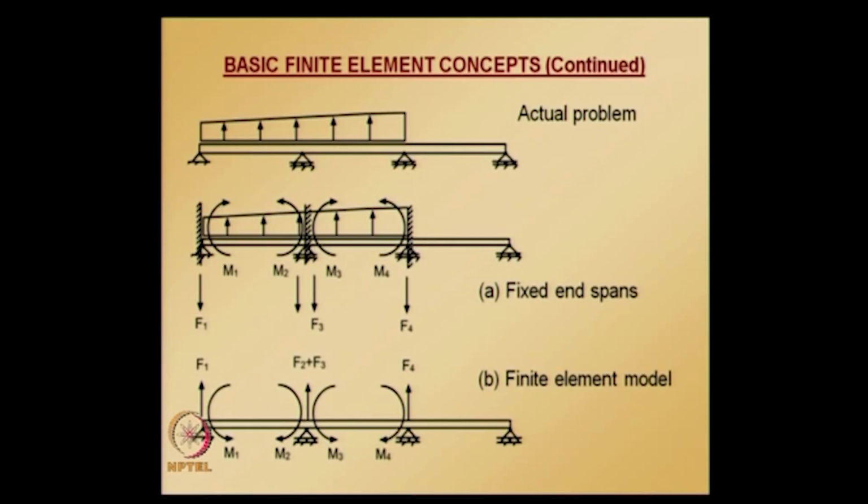Thus the final element forces and moments are obtained by superposition of the fixed end beam solution and the concentrated load finite element solution. Let us see how this superposition affects the computation of the element solution, and actually it affects only after calculating the nodal values obtained in the usual manner.